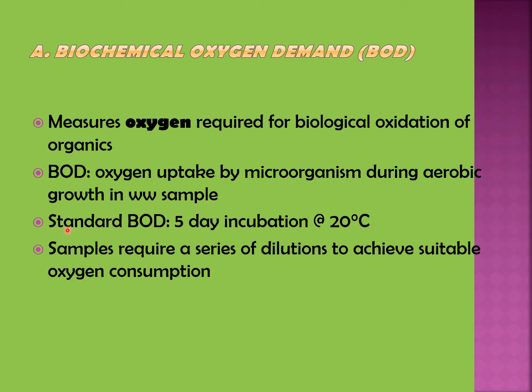The standard for the BOD test is a 5-day incubation at 20 degrees Celsius, or a 10-day incubation period. Among them, the 5-day BOD is most commonly used as it requires less time. The 5-day BOD is about 68% of the ultimate and the 10-day BOD is about 90% of the ultimate. Samples require a series of dilutions to achieve suitable oxygen consumption.